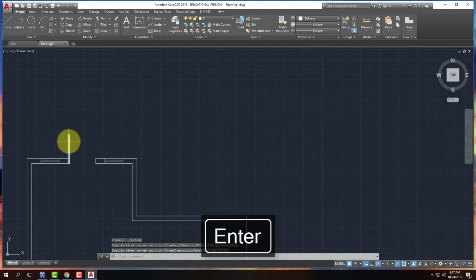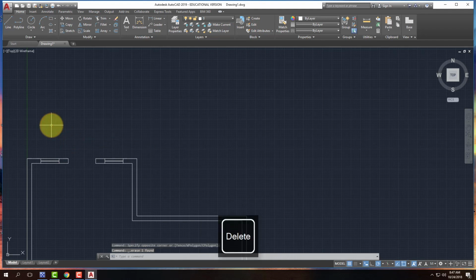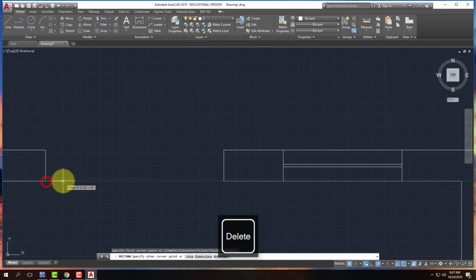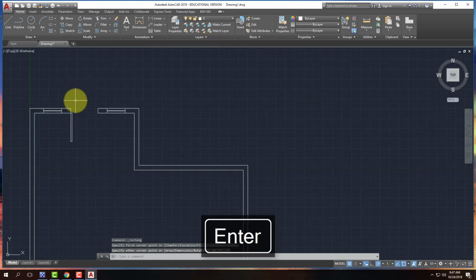And in that case, it gave me the door, but it gave it to me in the wrong direction. That was a mistake on my end. So let me do it one more time. I should have done negative 36 inches. So this is, again, at 1.75 inches, comma, this time it should have been negative 3 feet, because it needs to go down. And there it is, there.